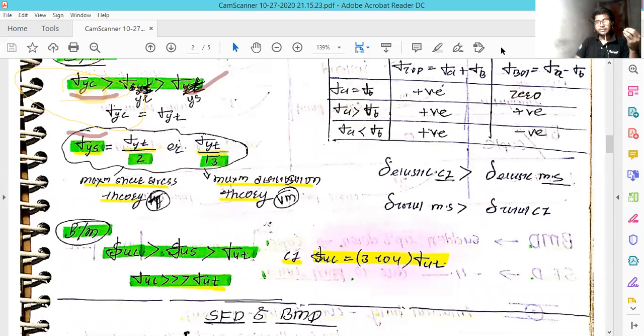So mostly cast iron is used for brittle material, and a lot is used these days, mostly for machinery, because it has good damping capacity in a brittle material. That's why it is used for machinery beds. Shafts are mostly not made from ductile material, because it gets deformed and is not able to transfer the power.